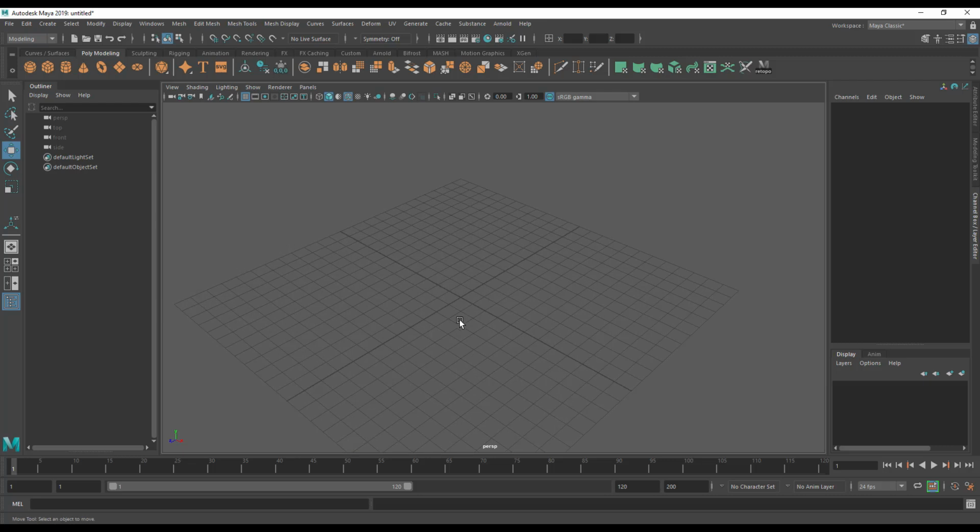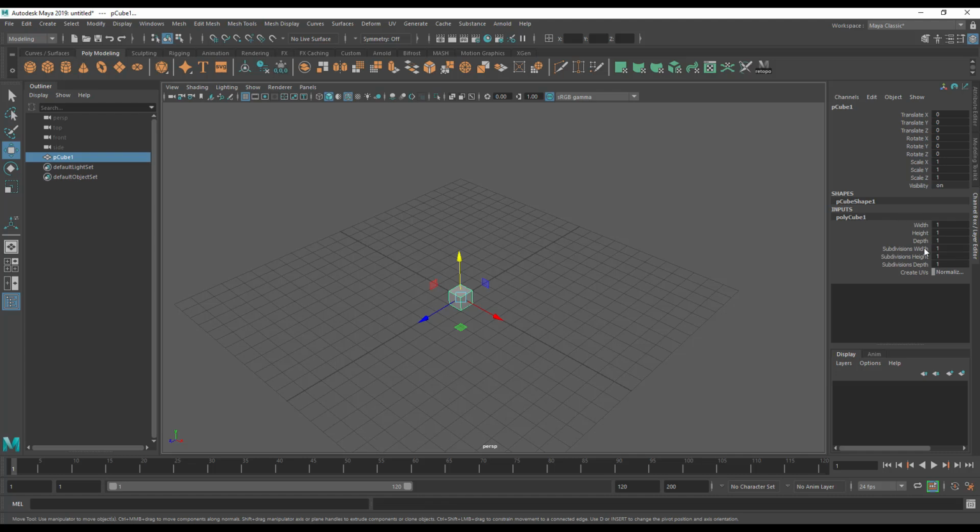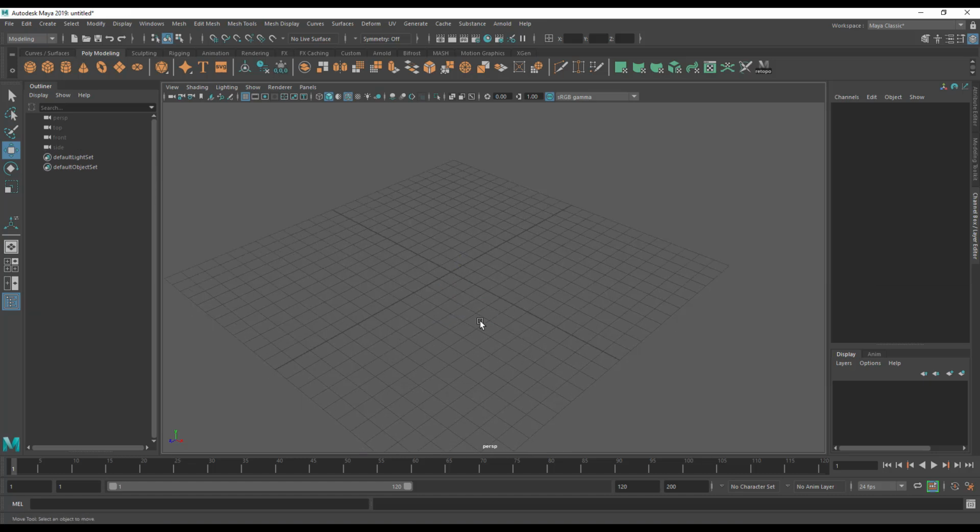Now normally in Maya I wouldn't do this, because even if I was creating something for a simulation that required a specific size, normally if it's 181 centimeters or 185, it makes little difference. In something like this, where we need ridiculously accurate measurements, however, it makes quite a big difference. So if you see me using the input node for scaling, that's the reason why. It's just a little more accurate. I can freeze the transforms. One thing to be aware of, however, if you delete the history on the object, you will lose this. So, there is a price to pay there.